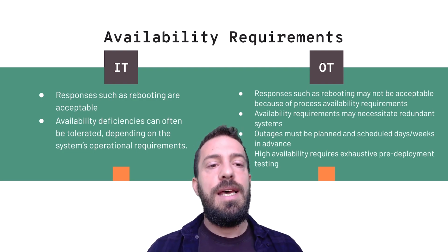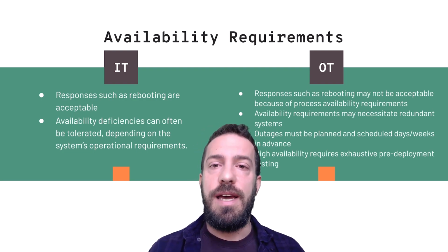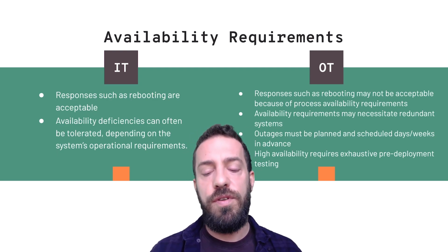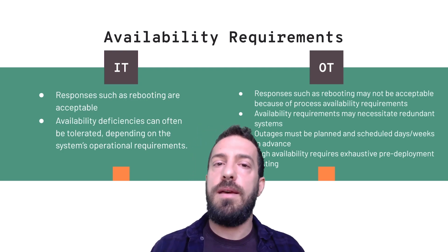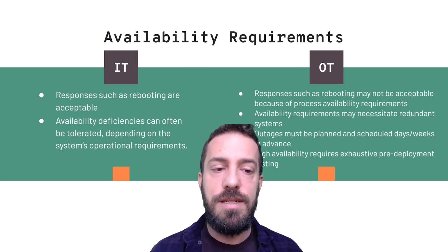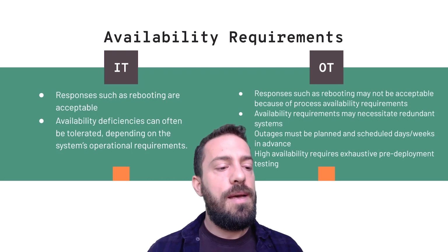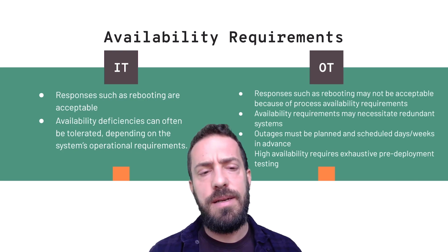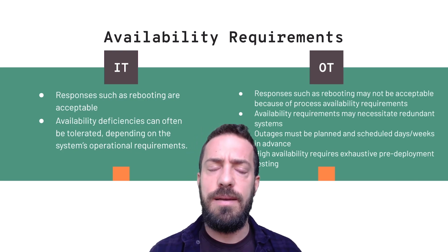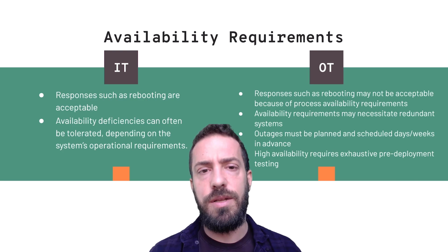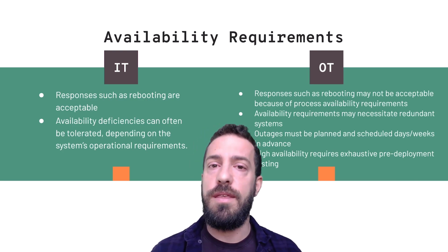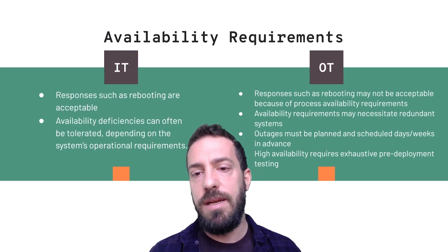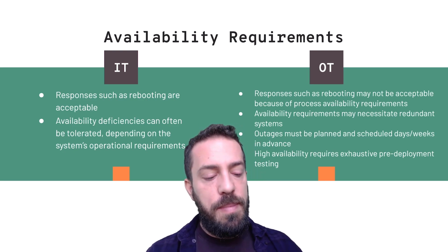Because even for example, you could not apply patches, right? If you think you're doing a great job in securing the perimeter of your network, then you think, this attack will never reach my PLC, so I don't need to patch the problem. But we've seen many times in latest incidents that this is not really the case. Attackers find their way through somehow, and you have to have appropriate mechanisms in different places in your OT environment. So patching is a problem.